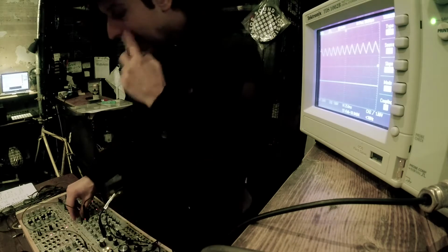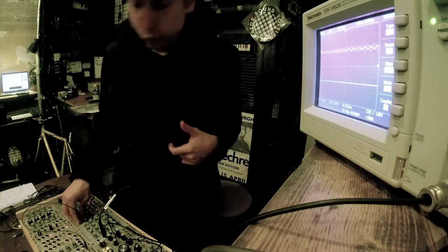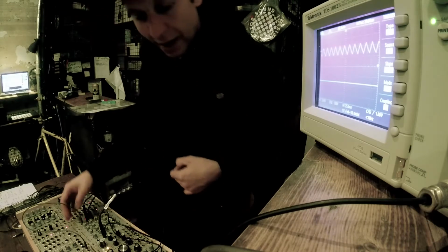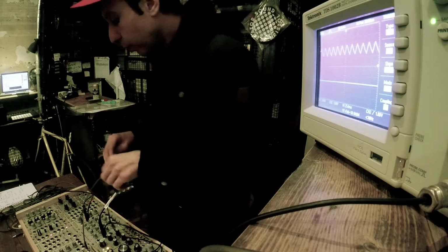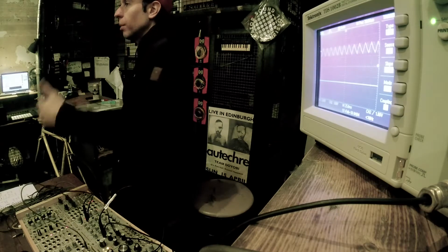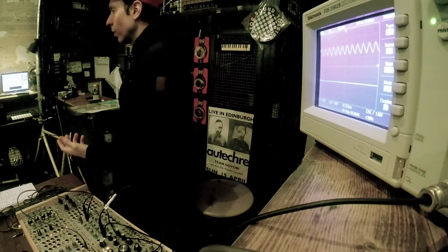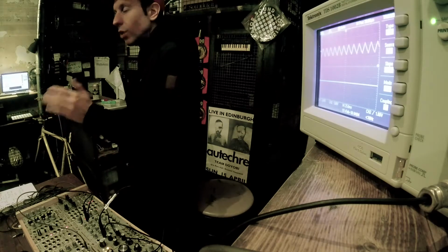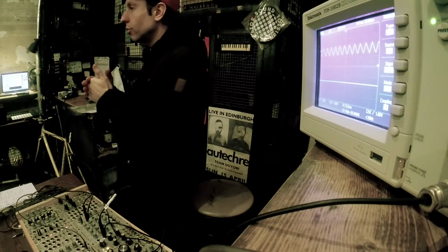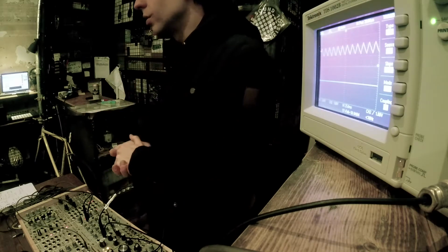So you see, actually it acts a bit like a low-pass filter, what you've noticed. Now, to be more precise, it acts a bit like a low-pass gate. So we haven't talked about those yet, but low-pass gates have one thing in common normally, is that as they remove the low frequency, they actually end up with silence. As the filter comes down in frequency, the amplitude comes down as well. So it is a process that relates more to the gradient of the signal, because if you start limiting the gradient, which is something that we do here, as you keep limiting, the amplitude of the signal goes down as well.